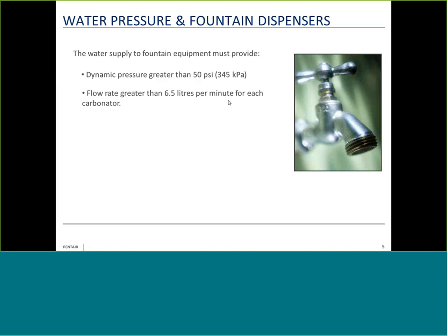And they tend to be carbon-vane pumps. And carbon vanes will shatter if they are not constantly bathed in water, because they produce too much heat, and when they cavitate, too much vibration, which causes them to break. If you've ever been back of house at a restaurant and heard a carbonator that's starved for water, it creates quite a bit of ruckus, a very loud noise that can be heard front of house quite easily.